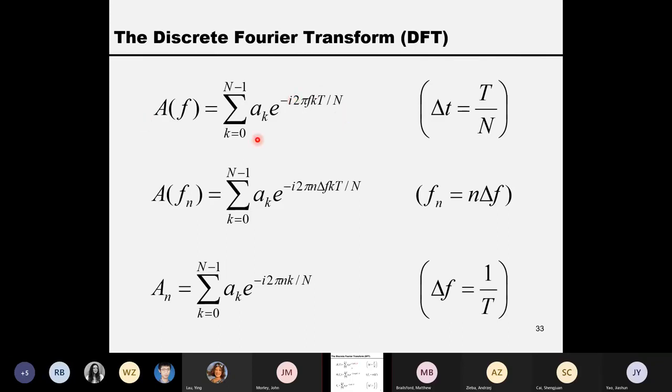Now, this function, of course, is just a time sample that became digitized, but the frequency still continues, right? So now you say, okay, because everything is in the computer, the frequency also must be digitized. So we digitize the frequency: Fn equals n samples multiplied by delta f. Delta f is the frequency interval. And then you end up with this formula. You just replace the smooth f with delta f multiplied by n here. You can see that. Okay.